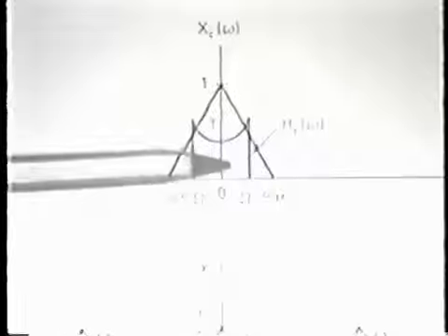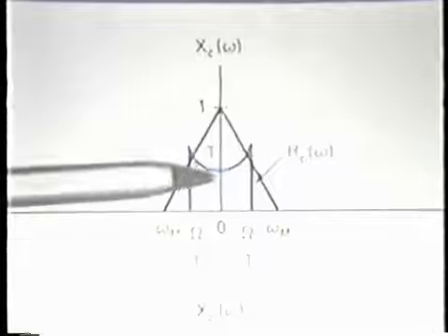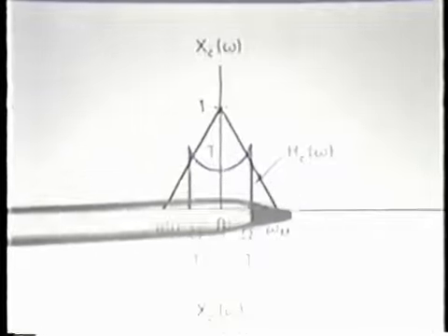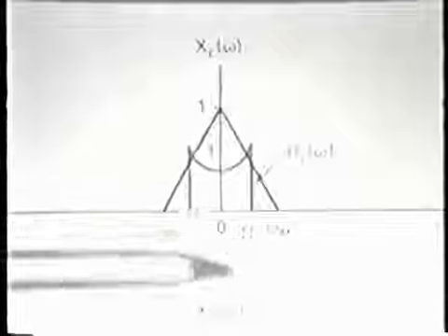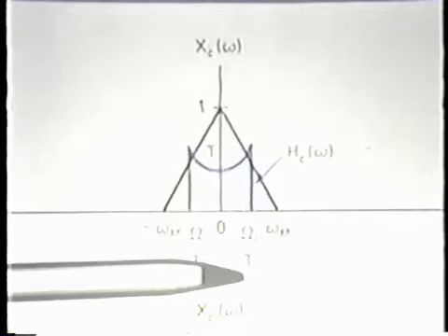So now the next step in the process is the reconstructing low-pass filter, and what that extracts is simply the portion of this periodic spectrum around the origin. And so finally, then, the spectrum of the output of the overall system will be the spectrum of the input multiplied by a frequency response, which is the digital filter frequency response, frequency scaled by dividing that digital filter frequency axis by capital T.